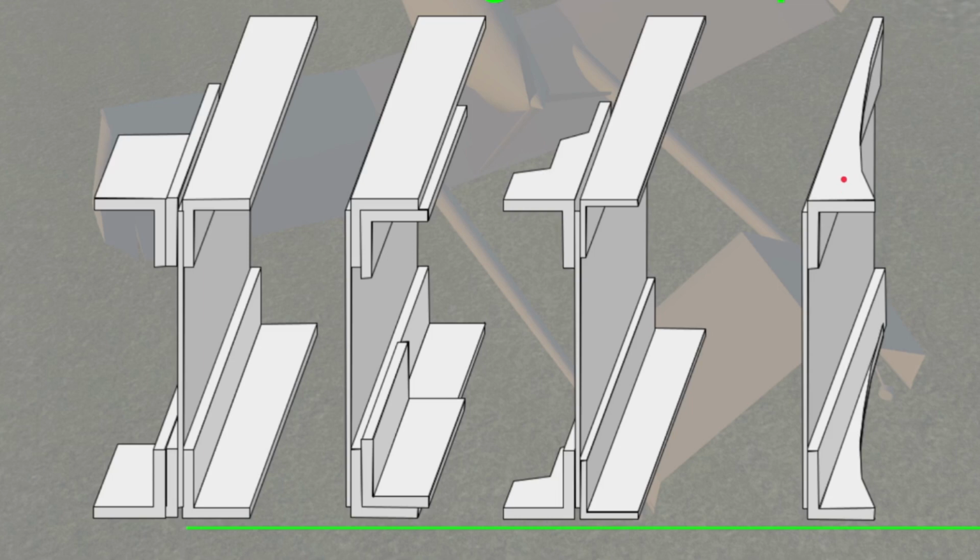Now over here, this is where we did away with steps and we did a gradual change in the size of this angle. Now, of course, this only has 1 angle in it, so it doesn't have nearly as much cross-sectional area as this one over here. So it'd have to be a lighter bending load on this beam. And I really didn't show any difference in some spar webs, but you can have quite a few different configurations of spar web too. So for a wooden spar, you can actually have some of the generally same ideas.